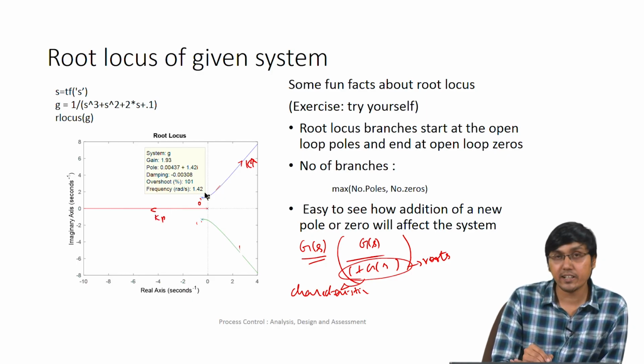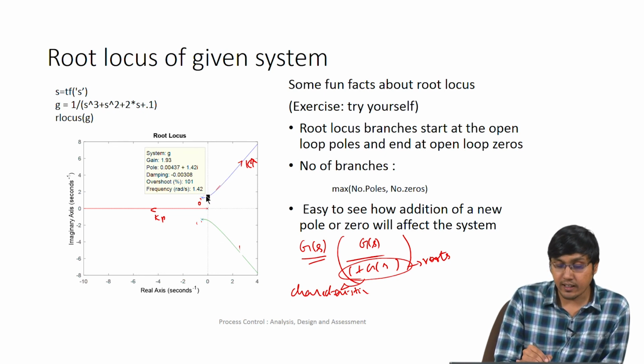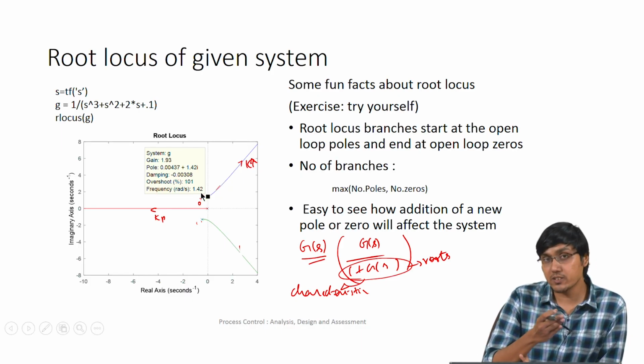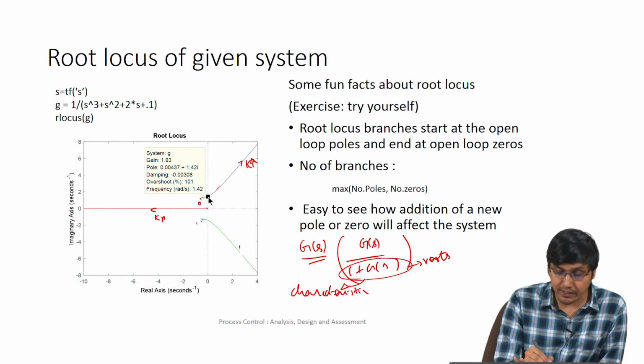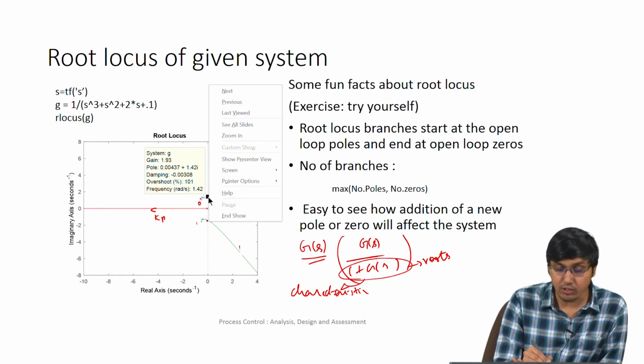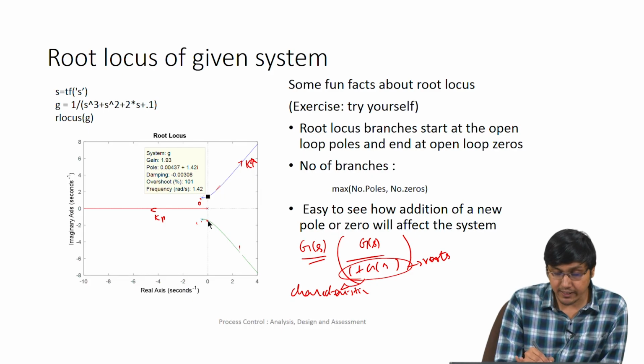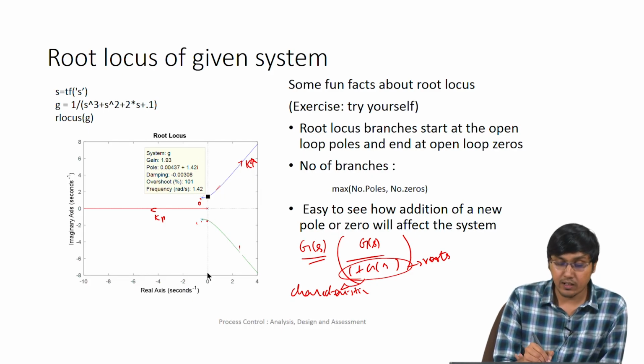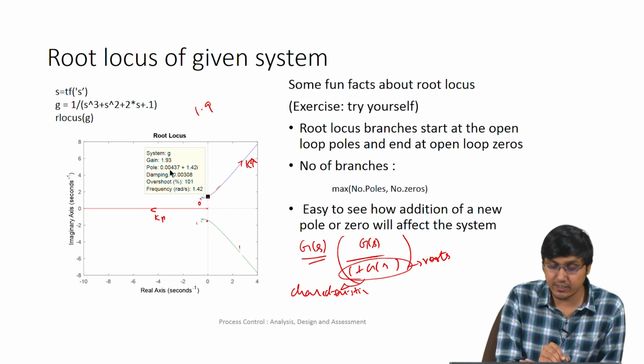So, for these two particular poles, whenever the gain increases, the root locus is moving, the poles are moving towards the right half of the S plane. There is a particular gain value wherein the pole is actually meeting the imaginary axis. At that point, approximately the gain here is 1.9. This is not exactly on the imaginary axis; it is somewhat tilted, at about 0.00437.